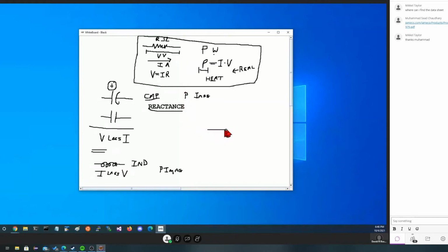So let's look at the complex number plane for a second here. In a complex number, which we might list like 100 minus J50, that's equal to some complex number over here, X. This is the real part. This is the imaginary part. Now, electricians use the letter J where mathematicians use the letter I. And the reason is just not to get confused with current being a lowercase i. But you'll see J in most math problems that involve electronics.